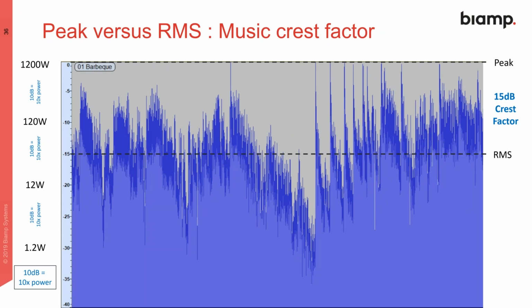So we can gain power by choosing the right driver. You can look at the sensitivity ratings of 2 different products and say, oh, I get it. I see a 3 dB difference in the sensitivity rating. Well, that's a free doubling of power. 3 dB is double the power. You can double your power just by choosing one product over the other. So it's an important thing to know. It's typically cheaper than buying amplifiers.